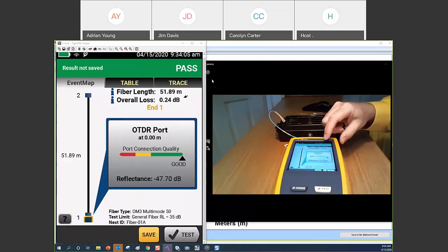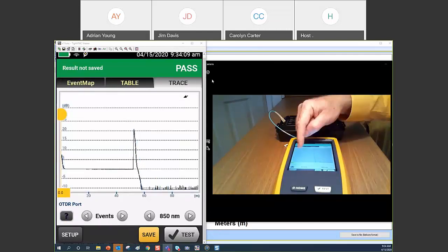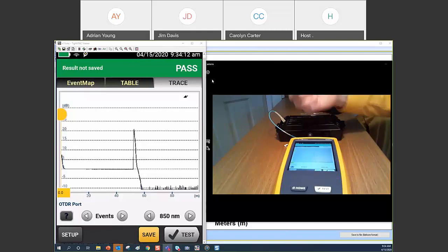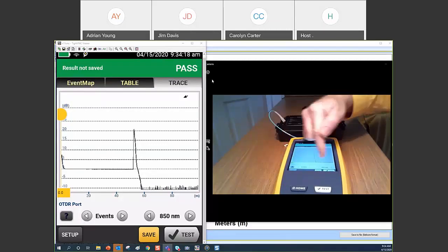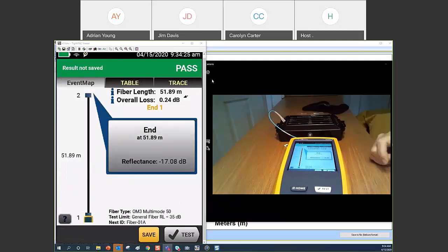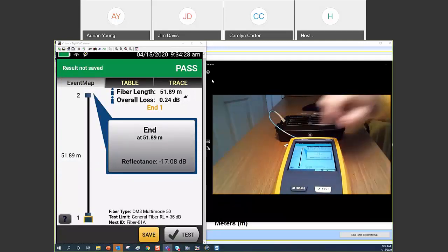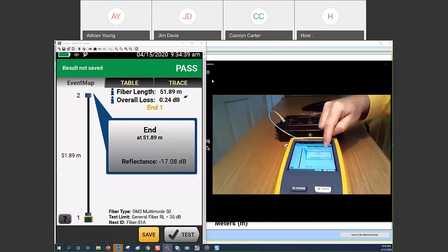Now, behind the scenes here is a trace. Let me go down to just one wavelength. And this trace is classic OTDR: the strength of the reflected event versus the distance to where the events are happening. Now, here is an expert module for the OTDR, and it is showing it's about 50 meters long, so we're done, right? Well, kind of, except I don't know if this connector is good, and I don't know if this connector is good. Let's go back to that trace for a minute.